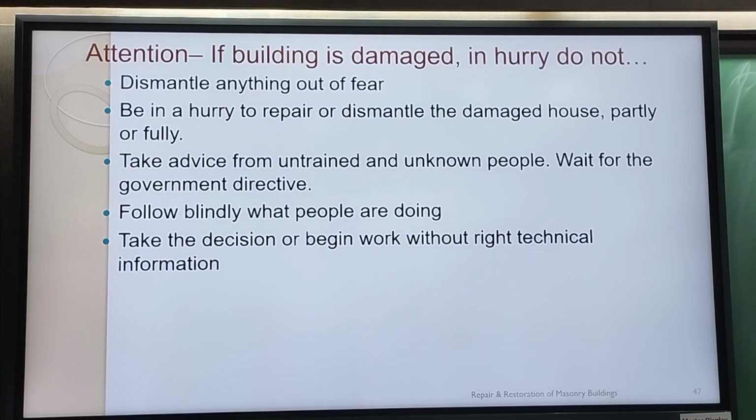In the 1999 Chamoli earthquake, it was very interesting. See, in most properly built houses, the damage will always be maximum on the bottom story because the inertia forces accumulate at the bottom. But in a poorly built house, because of the shaking back and forth, the whipping action causes the upper story to get damaged more. In Uttarakhand in 1999, in a lot of villages, the ground story was intact and the upper story had cracks in the corners. Every house you would see had cracks in the corner.